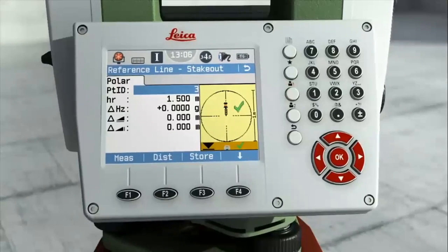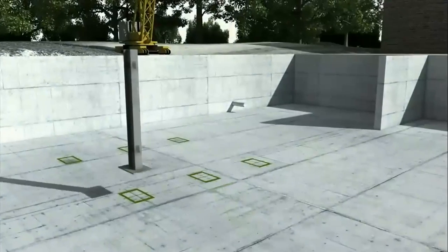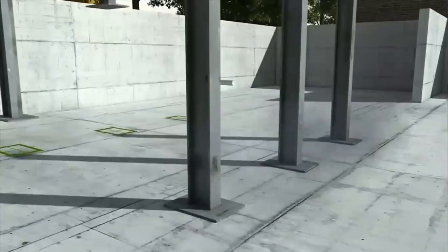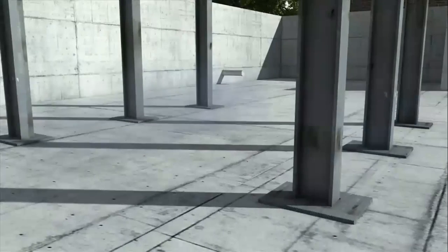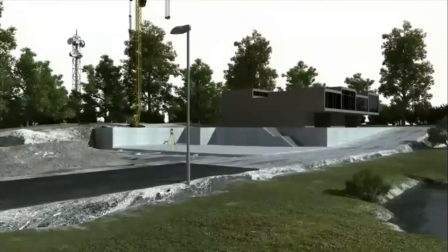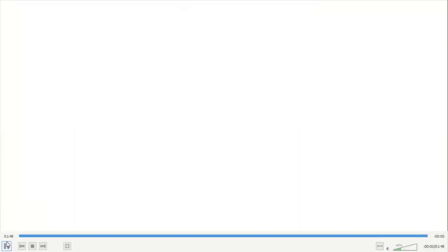The center of the prism can be adjusted by the horizontal as well as vertical screw, which is present on both sides of the total station. So the surveyor needs to rotate the horizontal as well as the vertical circle, and use the vertical screw for focusing on the prism. So this is how you need to take the reading from the total station.